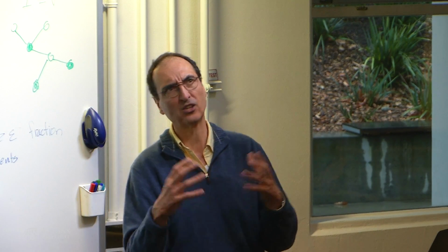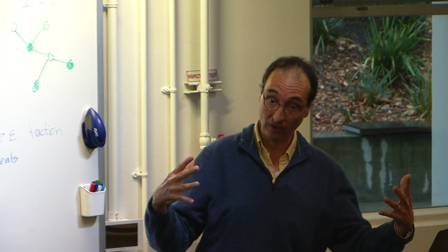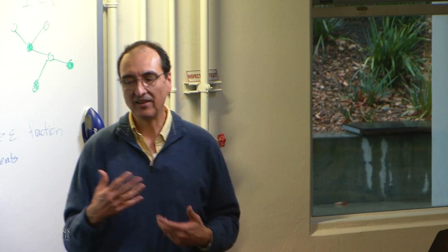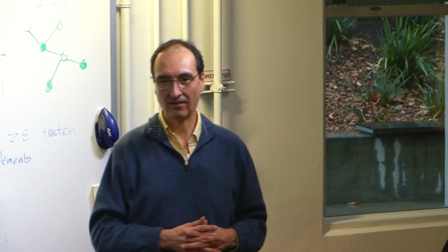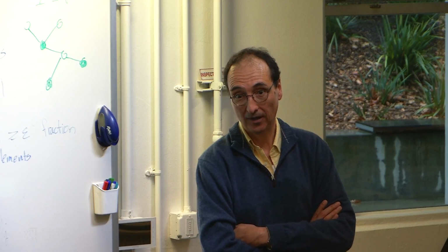I think it's cubic in the basic algorithm, and implementing it in BDDs allows you to solve very large problems. We'll typically solve things that might have 10 to the 9th states, so billions of discrete states between the specification and the control system. The algorithms for doing it are not particularly complicated, maybe a dozen lines of Python code sitting on top of a BDD library that implements everything.